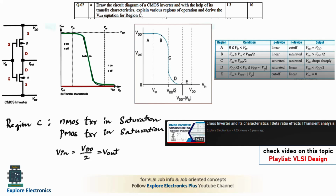And coming to the second part of the question, that is, derive the Vout equation in region C. It is very easy. At region C, both the transistors will be in saturation. It means both transistors are on. Both transistors are on in the sense the current will be equal. And we say Vin will be at half of the maximum voltage, and also Vout will be at half of the voltage. VDD by 2 is the output.